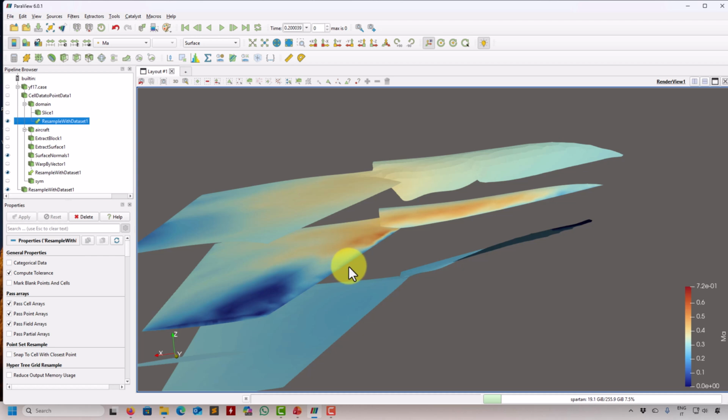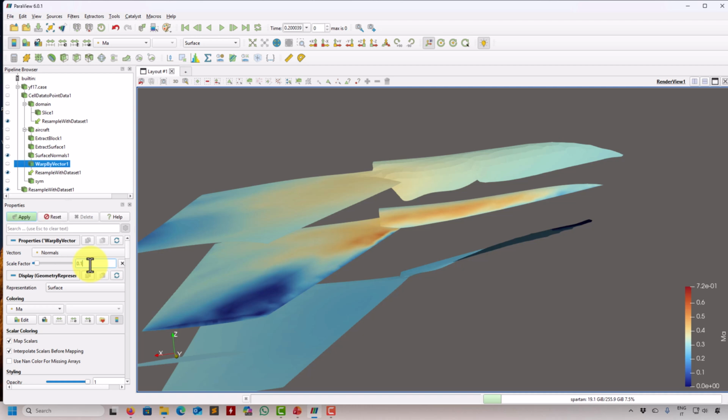Imagine that in this case we have velocity at the surface here, but if you run a Navier-Stokes, the velocity is 0. So you want to release streamlines from the surface, but velocity is 0. You cannot do it. What can you do? Well, you get the idea here. Just do warping of the surface, shift it a little bit from the original one, and then release from there, now that you get that velocity vector. So let's do it. So here I will put, for instance, 01.